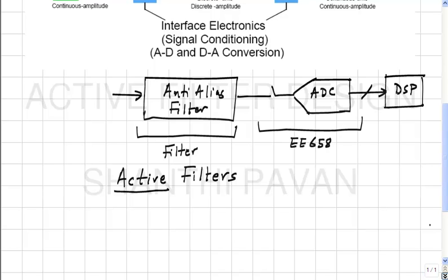Okay. All right. Now, at this point you just take it from me that sharp rejection means high quality factors for the poles, right? And if you want high quality factor, it turns out that you cannot get them with simply either RC or simply RL. You need both L and C and of course R. If you only had LC elements, then all the quality factors would be on the j omega axis. They would all be infinite, right? Which is again something you don't want. You want high quality factors, controlled quality factors. You don't want the quality factor to be moving around when temperature changes or when things age. So it turns out that you need both L and C as reactive elements as well as R.